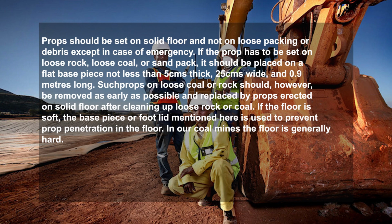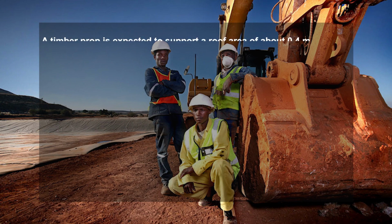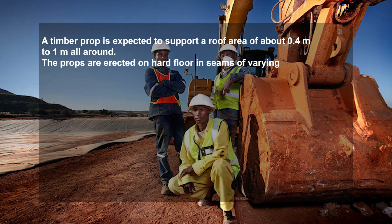If the floor is soft, the base piece or foot lid mentioned here is to prevent prop penetration in the floor. In our coal mines, the floor is generally hard. A timber prop is expected to support a roof area of about 0.4 meter to 1 meter all around. The props are erected on hard floor in seams of varying thickness as follows.